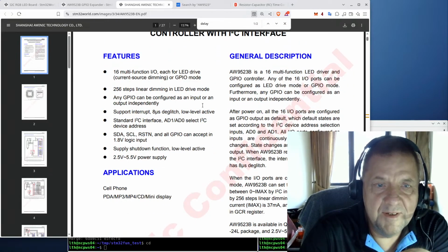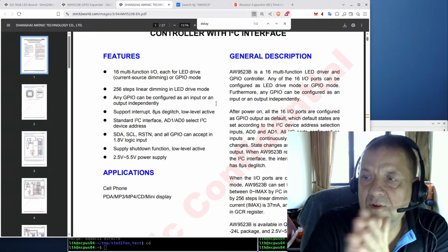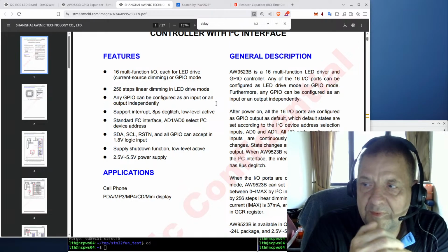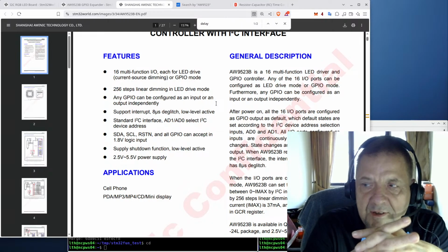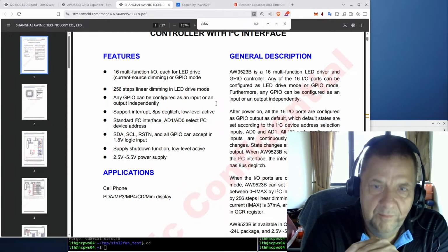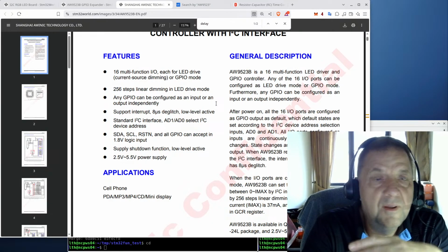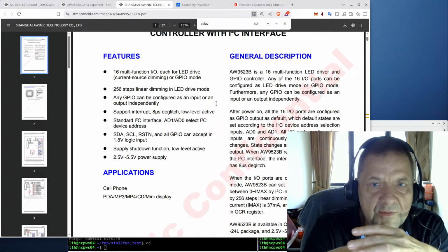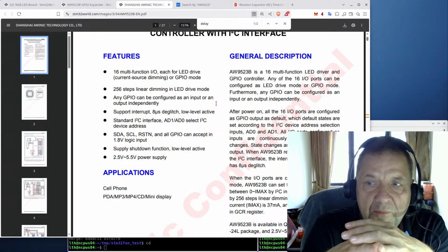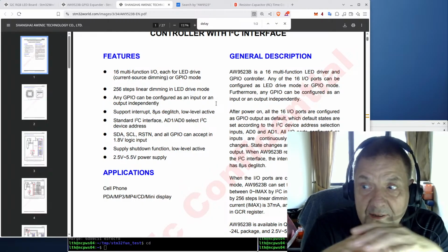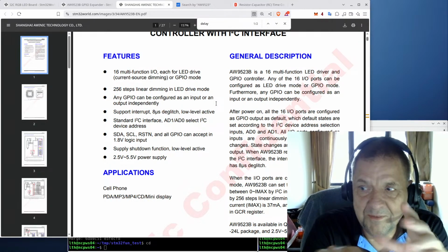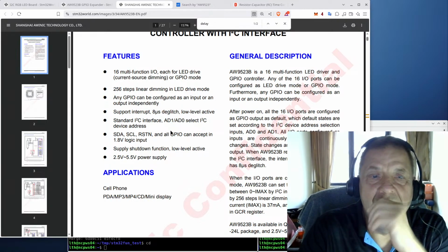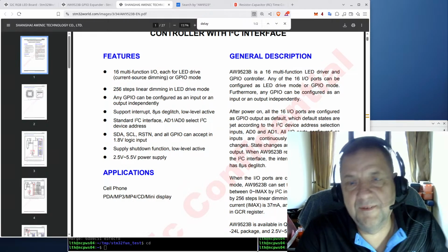The interesting part is that normally when you control the intensity or brightness of a LED, you will use pulse width modulation to rapidly switch the GPIO on and off. This one doesn't. This one actually controls the current. So if you put a scope on these channels when you're actually using it, it is actually completely regular voltage. It just regulates to control the current, and that is a pretty clever thing actually.